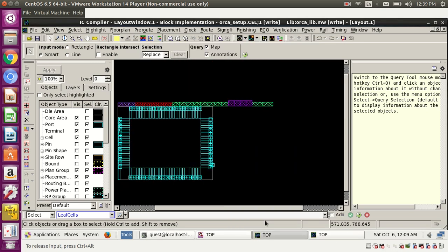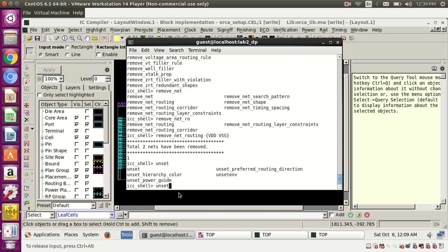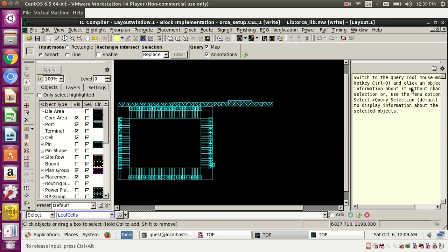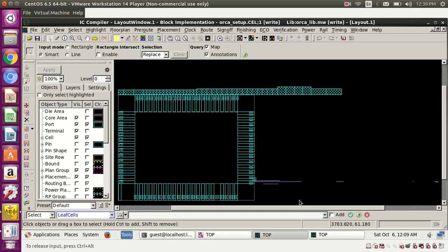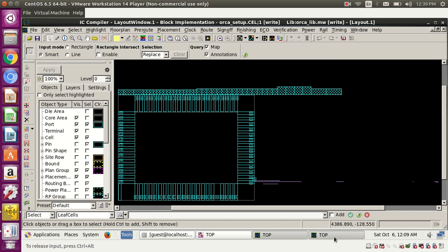So you may say, he has drawn a theoretical thing: the aggressor is rising, the clock is rising fast, and when data is going down, it may have a glitch here. That's the normal concept you have. So how does the tool take it? I'll explain simply. Forget everything you know. How does the tool calculate these glitches?